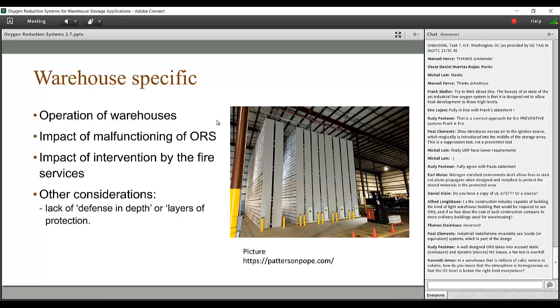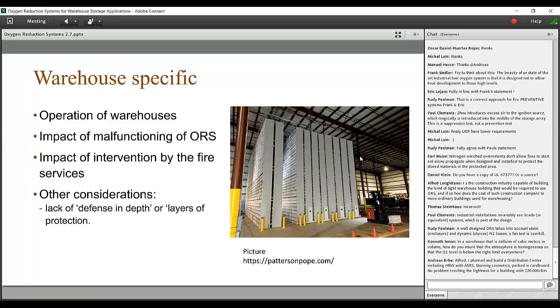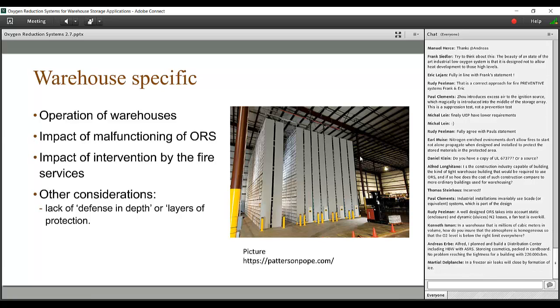I think what we found, again, from literature review, is that when you're into these automated warehouse facilities, when you have tightly compact storage and so forth, where having a gaseous type of prevention system could be more effective than having a water-based sprinkler system, for example, on its own, then that's a good application.